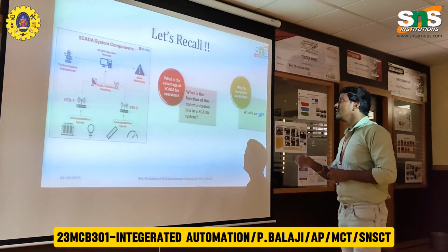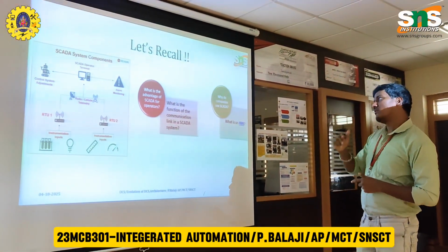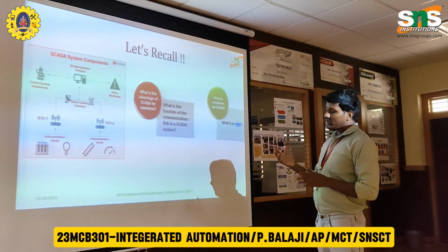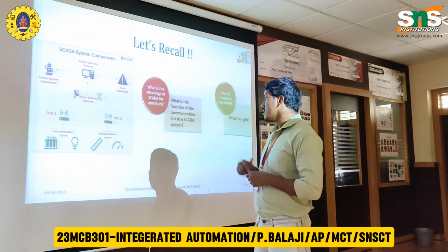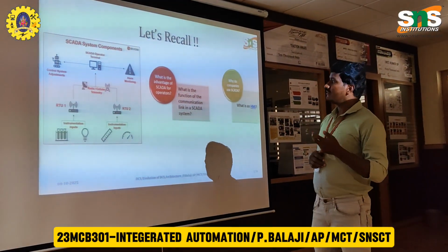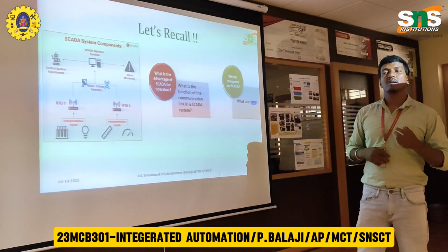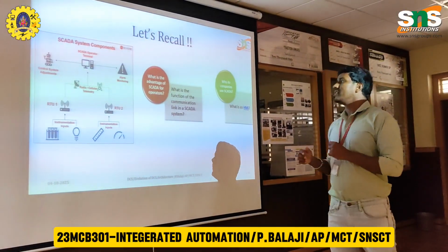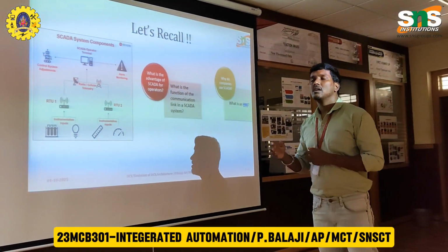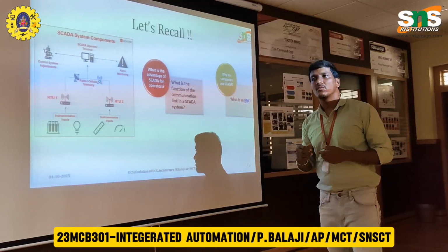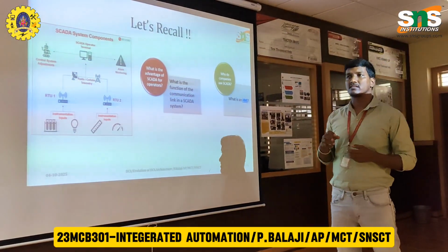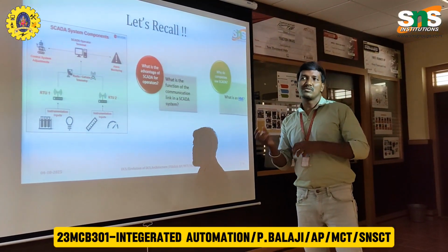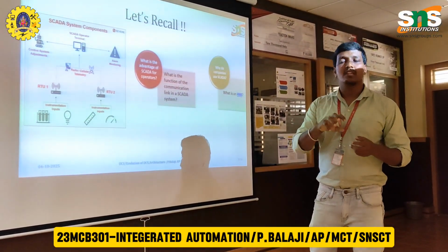We have four questions available. What is the advantage of SCADA for industry operators? Let me answer all those questions. When using the SCADA system, we expect a high accuracy level of output, and we can control dispatches and many kinds of automation applications. We can monitor and store the data, and by using the stored data we can rectify all kinds of industry specific problems.